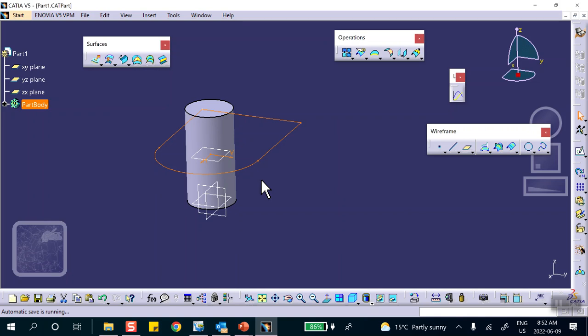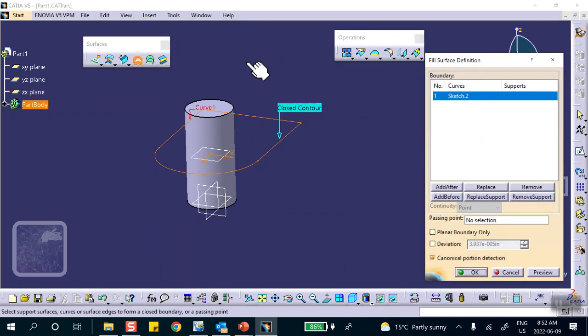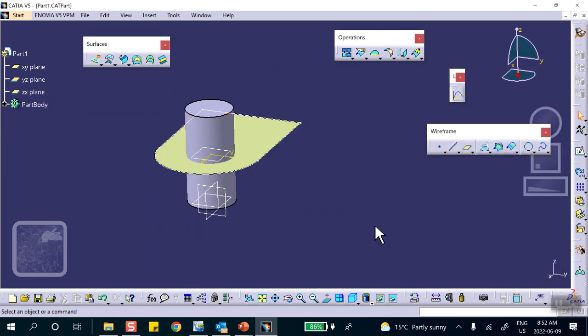It's called boundary. Look at the ways of making surfaces right there. You have done extrude and revolve; they were in the same group. This one is a boundary. As long as you have a closed curve, you can do that. If I had a hole in there, it will not do this. You cannot put a surface through something that has a little piece inside of it.